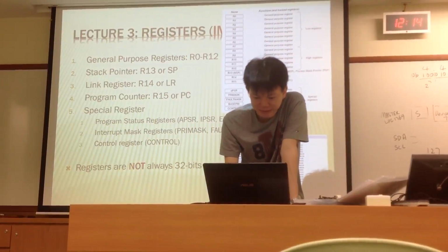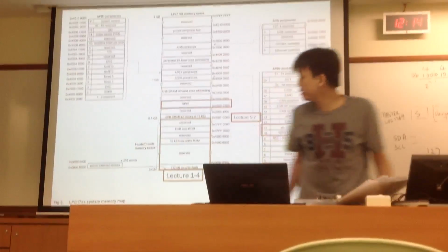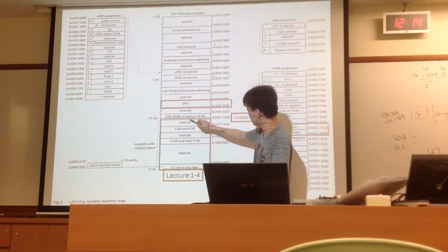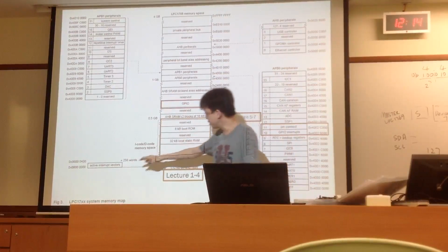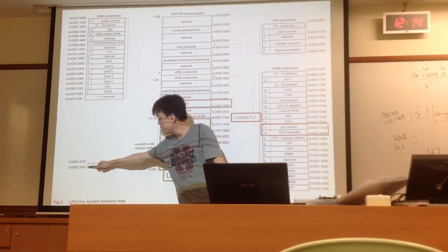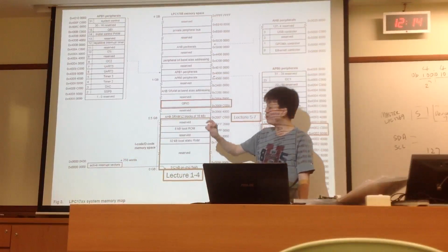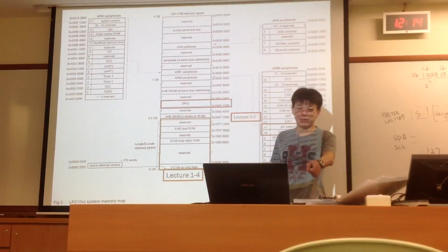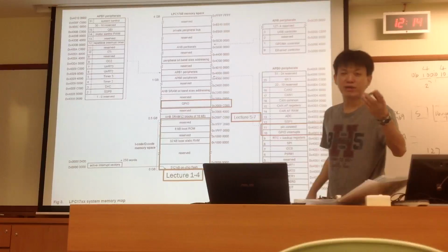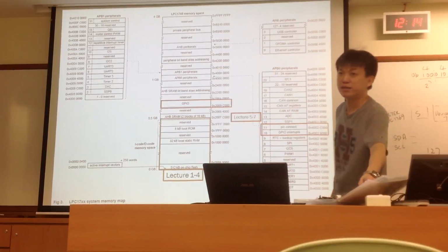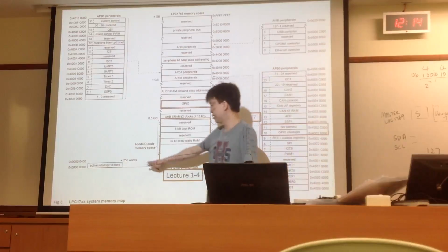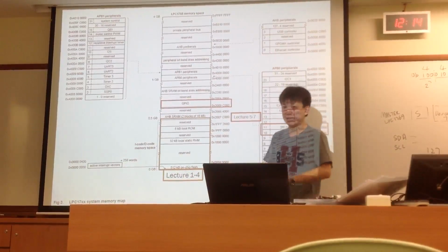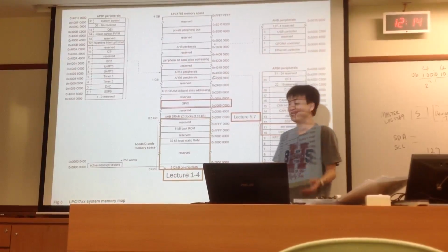So this is all the registers. That's what you have learned so far. In lectures 1 to 4 you use this portion. Later, for interrupts, you will use this portion. The first few 256 words. But I think the microcontroller you have only uses about 35 vectors. They don't fully use it. There are only 35 interrupts inside.